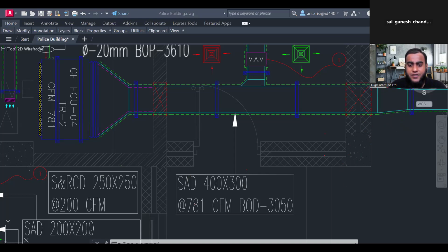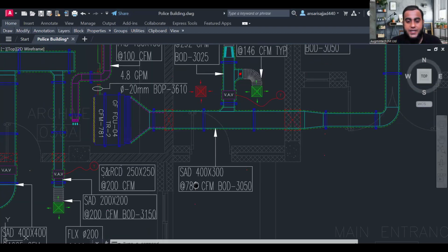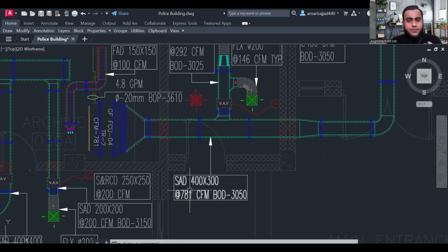So let's see first this one. From the McQuay duct sizer, we have different methods of duct sizing. In most cases for a residential or commercial application, we generally use the equal friction method. And for an application where cost is not an issue, for example a duplex apartment or palace, it is better to go for the velocity reduction method.